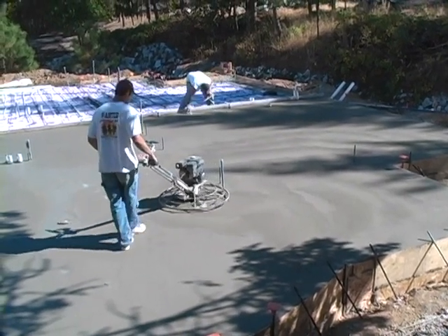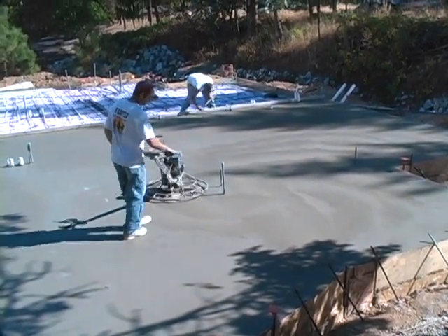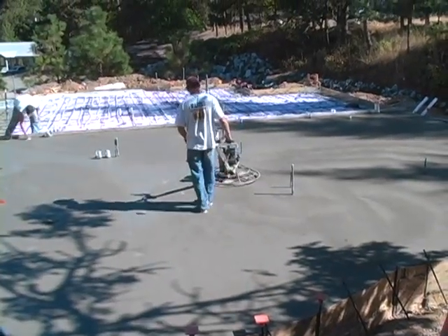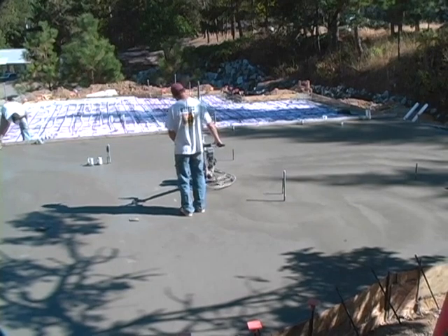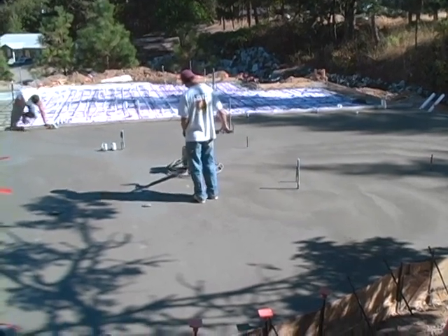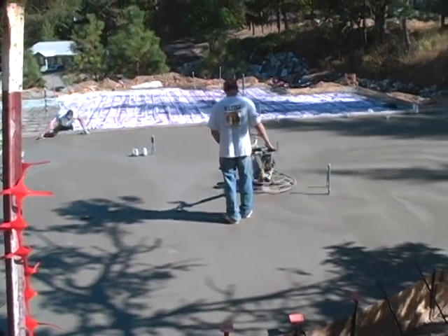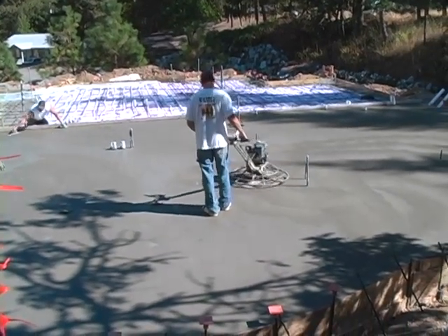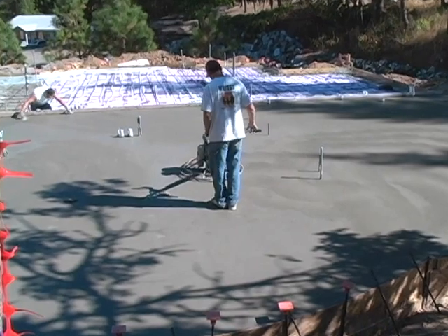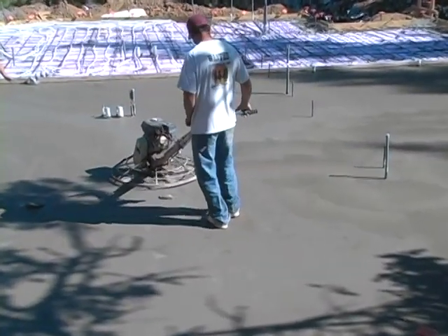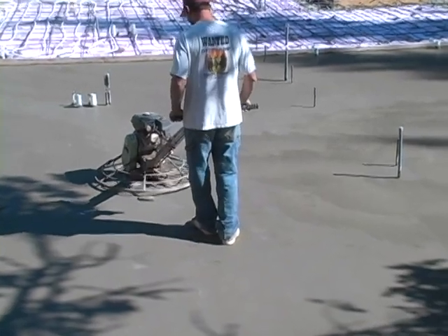Now you want to be careful if you're going to be doing any type of stained finish after this is all over. If you trowel too heavily with the power trowel, you'll actually seal the surface of the concrete so tightly and create such a sheen that the acid stain will not be able to penetrate deeply into the concrete and you'll get a weak stain. So it's an area where you need to be planning ahead for what you're doing next. But if you're going for a smooth, high sheen surface, this is a really easy way to get it done.